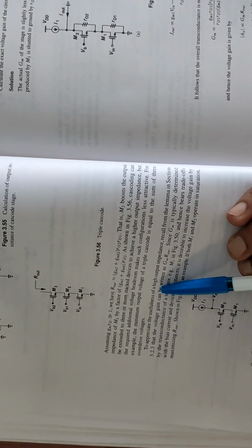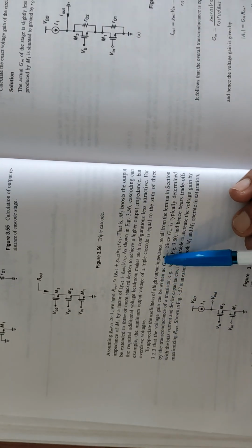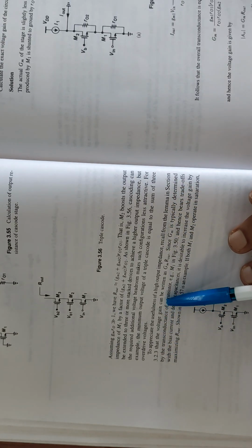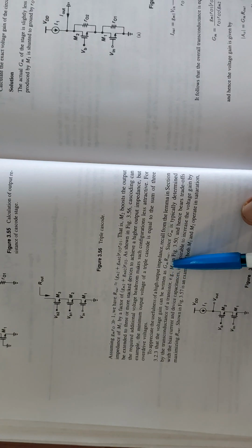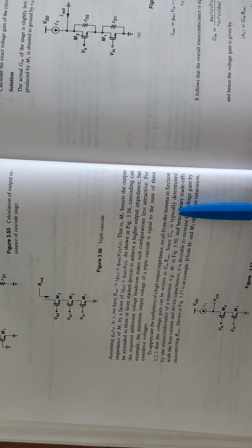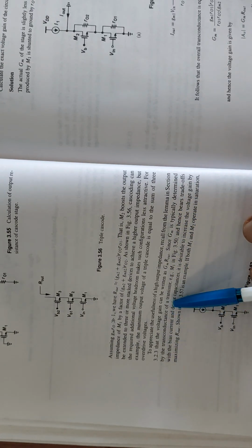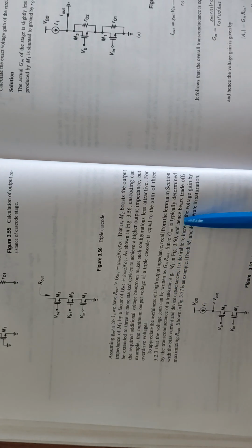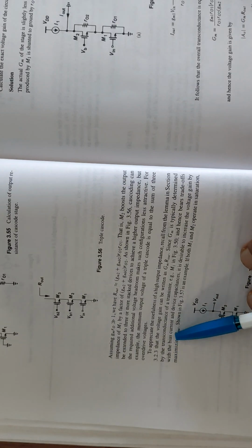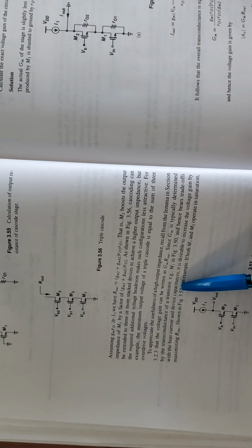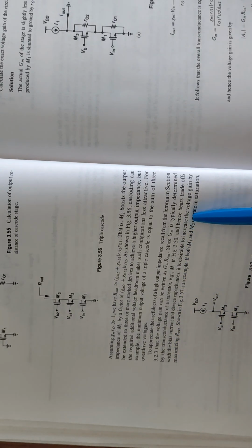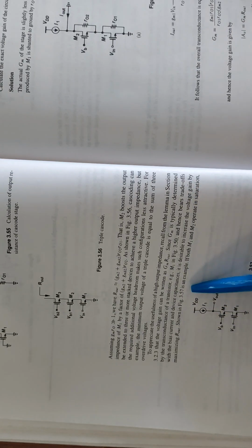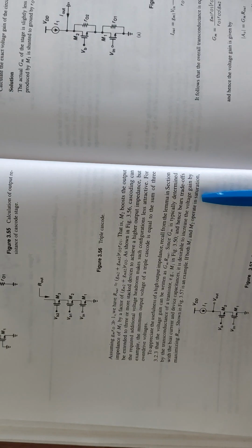To appreciate the usefulness of a high output impedance, recall from the lemma in the session that the voltage gain can be written as Gm Rout. Since Gm is typically determined by the transconductance of a transistor, for example M1 in the figure, and hence bears trade-offs with the bias current and device capacitances, it is desirable to increase the voltage gain by maximizing Rout. Shown in the figure is an example where both M1 and M2 operate in saturation.